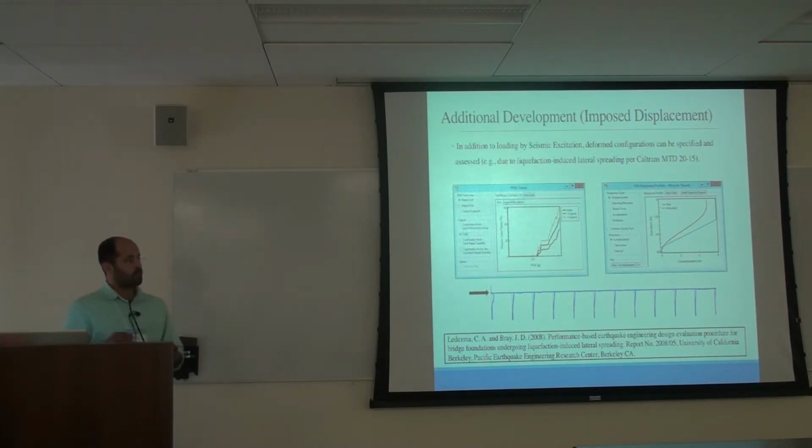Additional development is not part of this project, but we are working on it. If you want to perform liquefaction-induced lateral spreading in this kind of analysis, also using MS Bridge, it's the same analysis, can be found in Ledesma and Bray, 2008, and Professor Bray is here today. So we can apply the displacement, imposed displacement along the pile height to represent the soil movement after liquefaction.